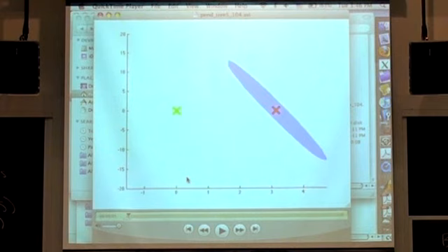We've seen cost to go functions; these were ellipsoids around the fixed point. I do a sums of squares optimization to verify that this function is negative definite, which involves a higher order polynomial expansion of the dynamics in this form. And I try to find the biggest contour for which that system is still negative definite. That's sort of all the detail.